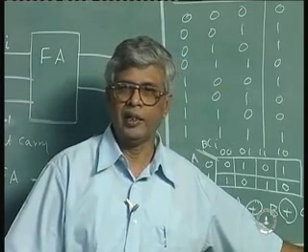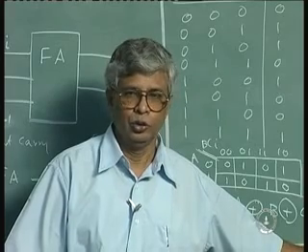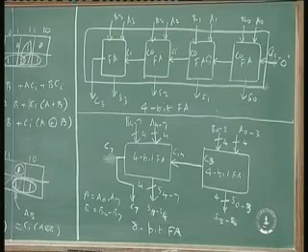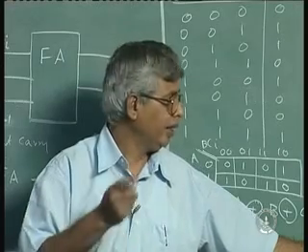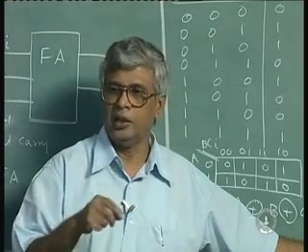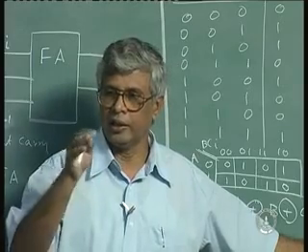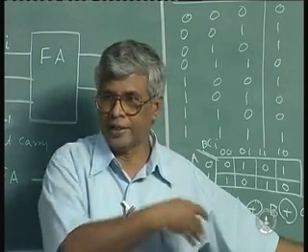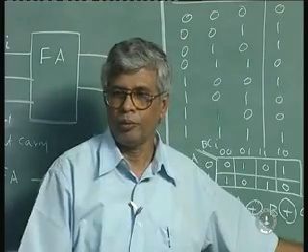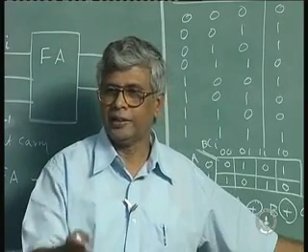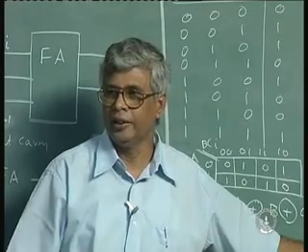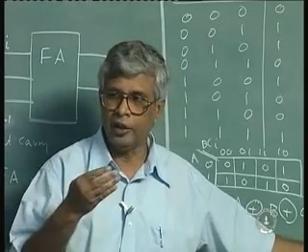The concept of carry in, carry out, sum. Individually each of these blocks will have A exclusive OR B exclusive OR C as the sum, and AB or C (A exclusive OR B) as the carry circuit. So there are so many gates inside. Take it as an exercise. Find out how many gates will be there in a 16-bit full adder,